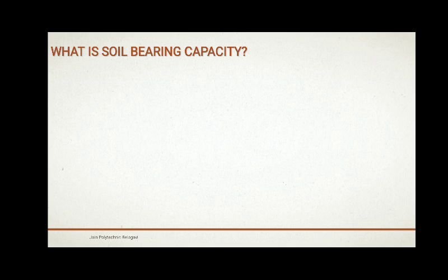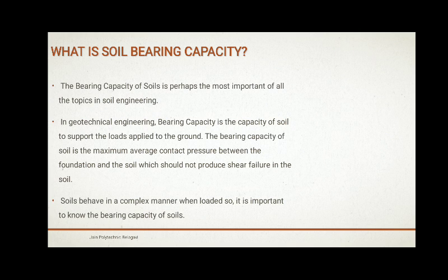Next, coming to what is bearing capacity. Bearing capacity of soil is the pressure the soil can take from the upcoming structure. In technical terms, the bearing capacity of soil is perhaps the most important of all the topics in soil engineering. In geotechnical engineering, bearing capacity is the capacity of soil to support the loads applied to the ground. The bearing capacity of soil is the maximum average contact pressure between foundation and the soil which should not produce shear failure in the soil, which means the limit up to which the soil can bear the loads coming from the structure.